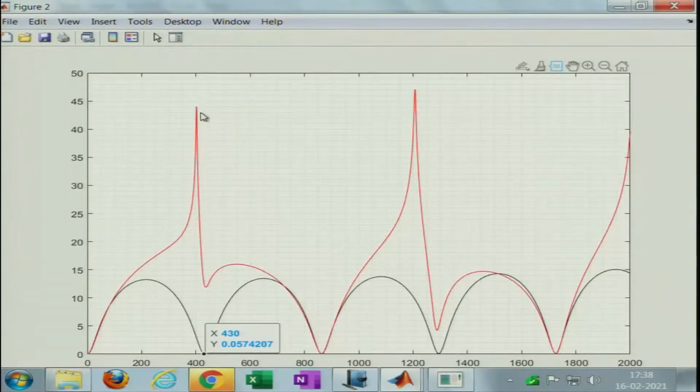Okay. Now, we have the peaks here. So, what do we do with this? Basically by L by 2 we cannot really just tune it, we have to tune the length, and anyways these are all based on plane wave models. So, this will obviously fail, there will be some higher order modes generated at the interface between the inlet pipe extensions and the annular cavity. There will be higher order modes generated due to the inductive effects of the evanescent modes. The effective length or the acoustic length of the pipes will increase. So, in order to tune that, we have to consider the geometrically smaller length.